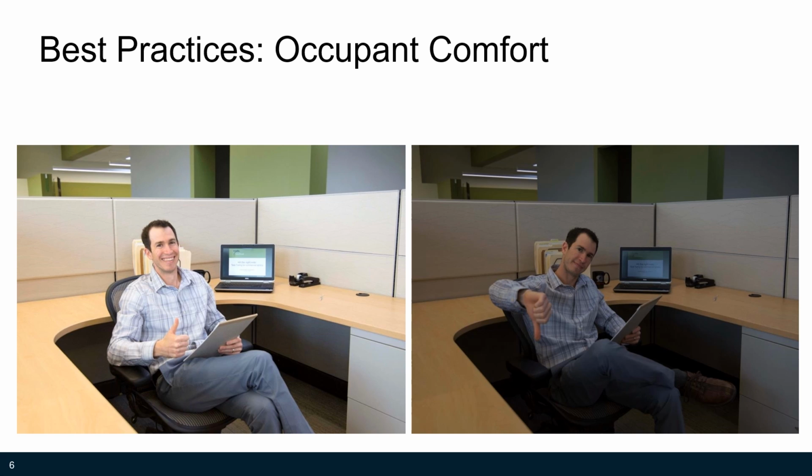Because of this complication, we recommend incorporating occupant feedback into the task tuning process in order to strike the right balance between energy savings and occupant visual comfort. Although this may result in lower immediate energy savings, it's likely to increase energy savings persistence, as facility managers will be less likely to override tune controls because of occupant complaints. Anecdotally, you may be surprised to receive feedback that an even lower light level is preferred, as has been the case in several instances across various demonstration projects.